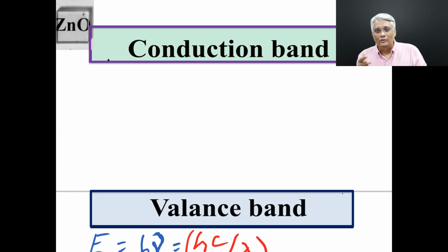If I want to have a top electrode, and the device is emitting light, of course, the light has to come out of the device. You can't afford to have a normal conducting layer as a contact electrode, right? Light cannot escape through that. So you need a material that is transparent as well as conducting.